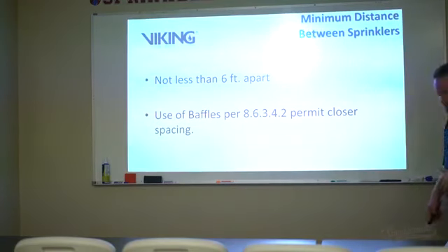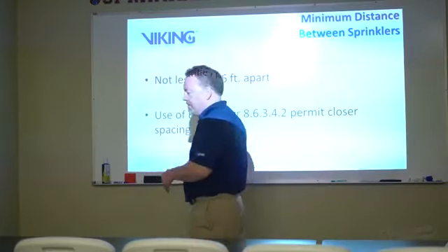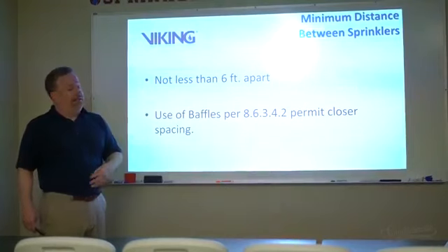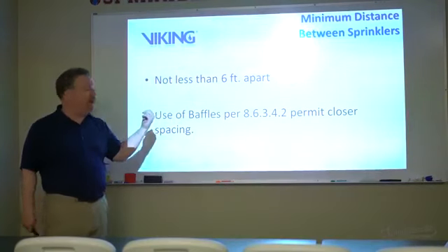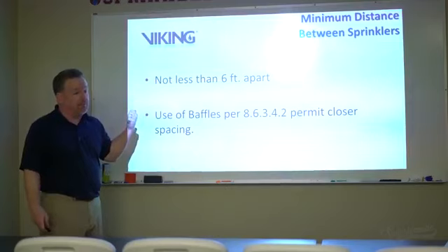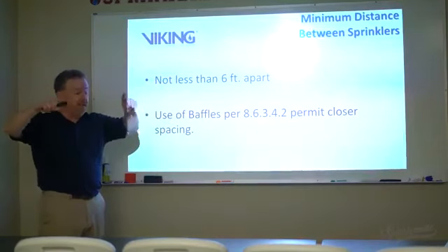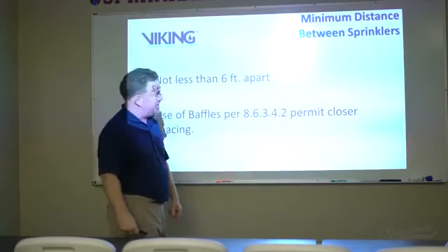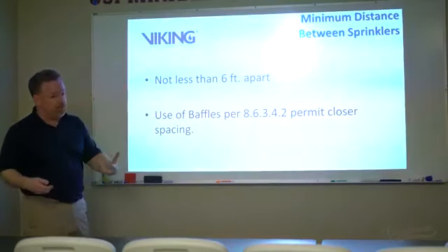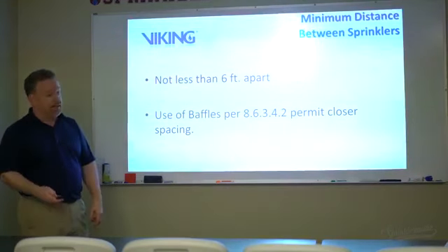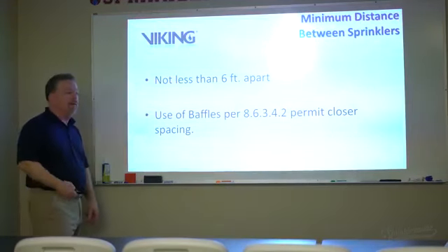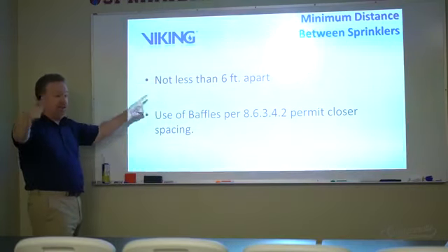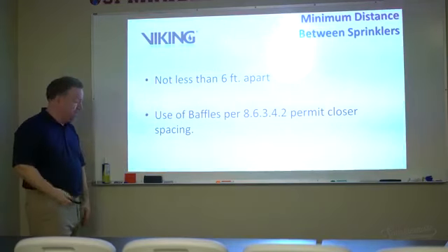Well, like that other picture you had where you had the mill construction where the beams are in there. Right. Every void could have one in theory. In theory, yeah. Well, and in that particular case, every unit is one. So you're going to wind up in a situation like that where you've got that deep, you're putting sprinklers in each of them. Yeah. That becomes the big challenge with obstructed construction like that. You wind up with a lot of sprinklers, because it obstructs the spray pattern within that 18 inches. So you have to have them in each unit, right?